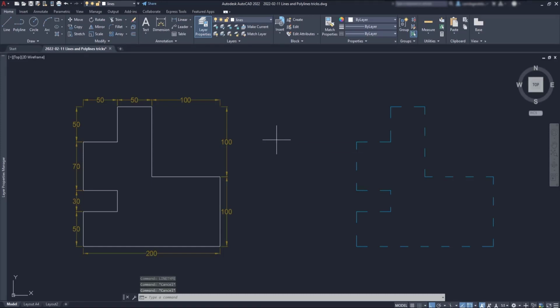The default value, as you can see, is 1, and this drawing has the dashes with this size. If I change the scale to 0.5, you can see the dash sizes are now half as small. If I am not happy with the result, I can keep changing until I find the size that works for me.